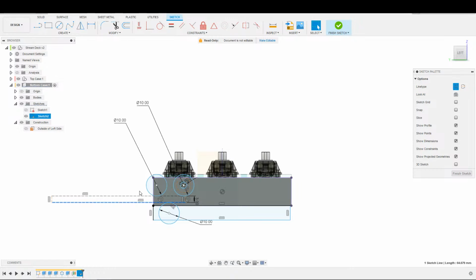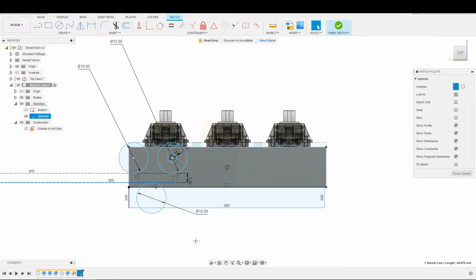Alternatives is just to have it sliding on plastic, which we talked about before. So at this point, because we got to make this that much bigger, and I was trying to keep this relatively low profile, because even though we have plenty of vertical space, as I said before, it's the same idea behind not including the Arduino space in each of these cases: if you don't need to print the extra stuff, then we just plain don't, right? So that being the case, let us abandon this idea of the bearings. I liked it, but it's one of those things that's going to cost us too much at this point in design to implement. We just got to add way too much that is unnecessary, and let's go back to just a rail.